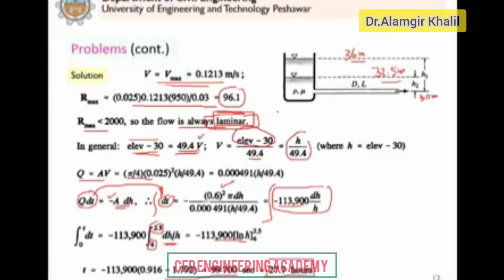Similarly, flow can be uniform flow, it can be non-uniform flow. Similarly, the flow can be steady flow, the flow can be unsteady flow. We can have a steady uniform flow, a steady non-uniform flow, a steady laminar flow, a steady turbulent flow. Don't try to mix things, because in laminar flow we consider that the velocity profile is not changing in the x direction, it is a steady flow. Clear? That's why in the beginning I told you that these are different concepts. Don't try to combine them.